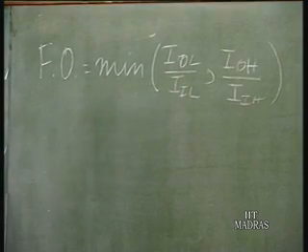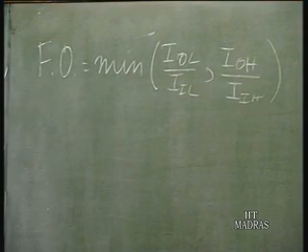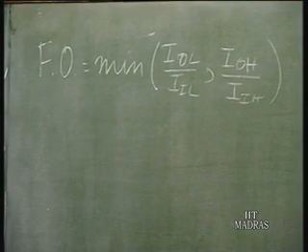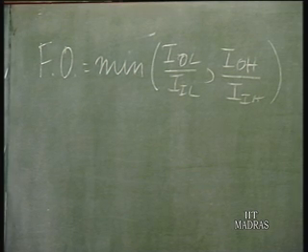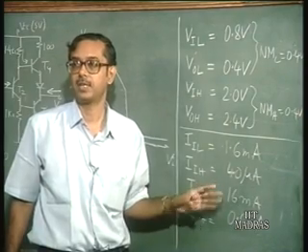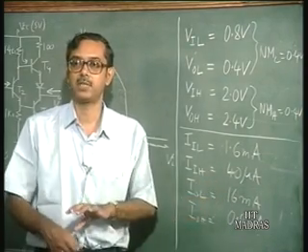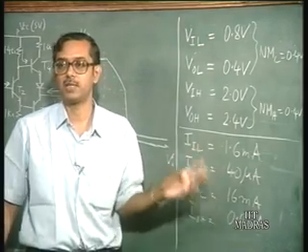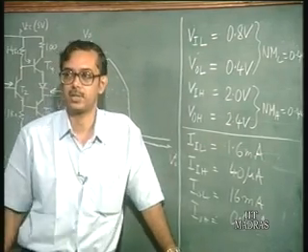In this case, of course, both are 10, so there is no problem, but in many cases, this is very important when you are connecting two different logic families. For example, you have in a circuit both a CMOS NAND gate as well as perhaps the 7400 series.